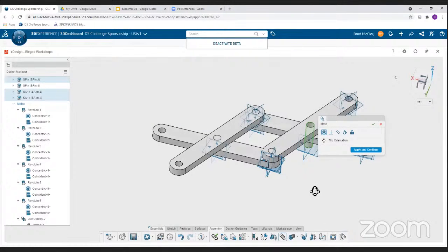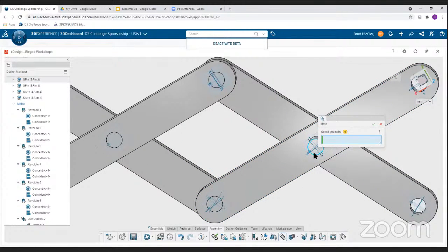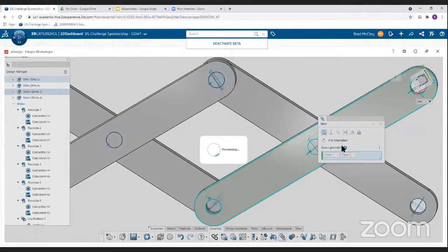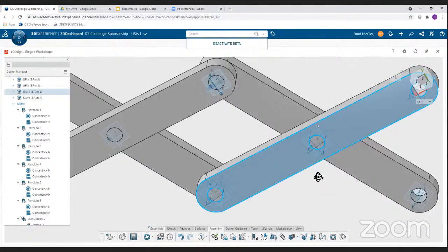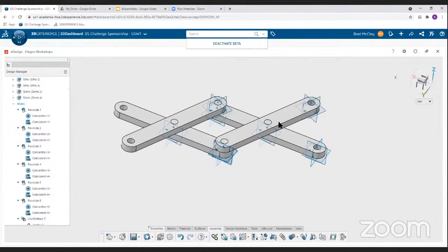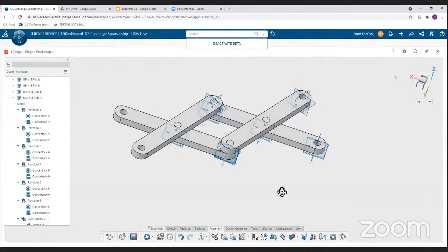And our sketch is starting to get a little more defined now, so we won't need to define everything this time, because the arm already can't really pop off based on some previous constraints we did. So we will only need to find this one relationship with this pin to make it coincident. Now, if we hit OK, this arm can't lift up, so it would be redundant to make this and this coincident, because there's no way it cannot be, because their coincident mate is here. So these two can't separate no matter what we do.